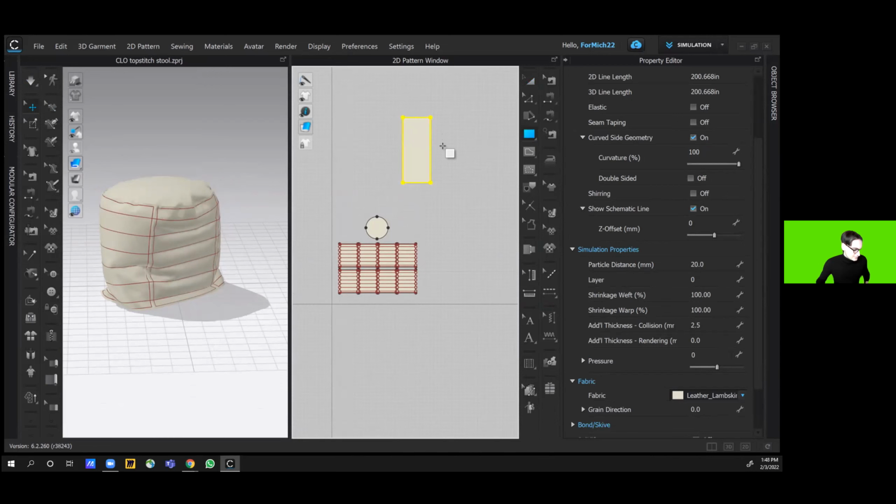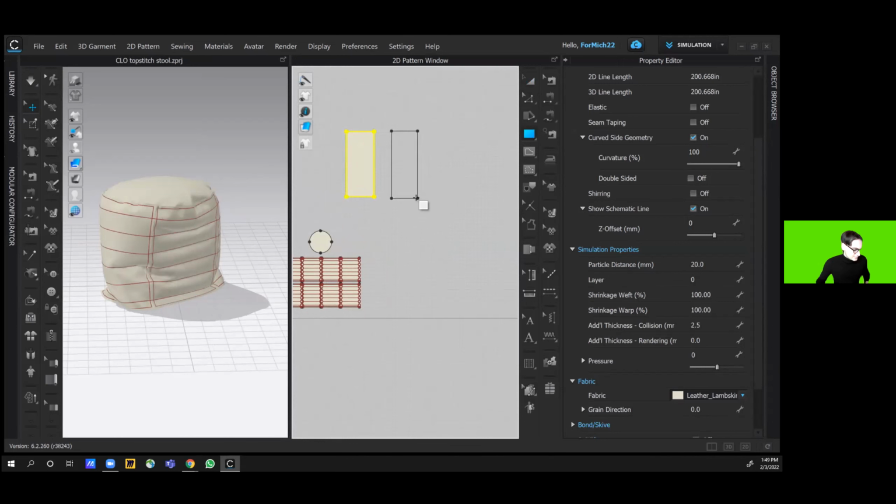So the way in which you would do that would be similar to the workflow we did last week, where let's say we import the cylinder from Rhino, and that comes in the way that everything we've uploaded comes in. And then you would create, like I am right here with the rectangles, two sides of something to wrap it. And then you would just orient them around the cylinder such that when you started the simulation, because remember how the sewing works is the lines are kind of magnetic to each other, it would be the sheath for that thing.